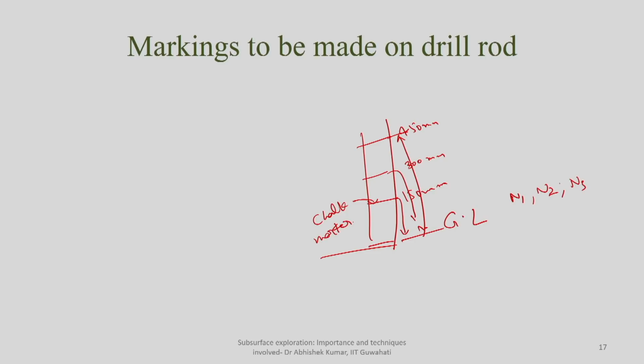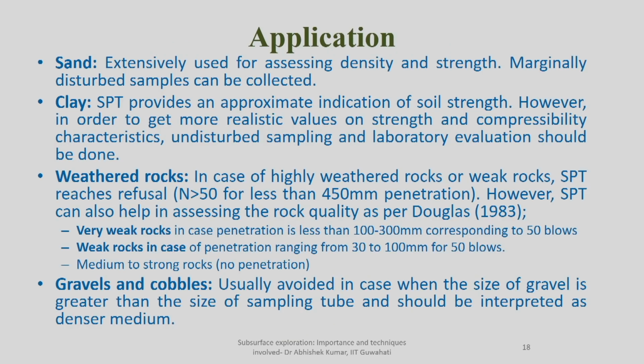For ease, otherwise, because it is pushing into the ground, how will you get to know it has reached 150 mm penetration? Then the application: it can be extensively used for assessing the density and strength of sands. You can even get marginally disturbed samples. In clay, it can provide an approximate indication of the strength properties.